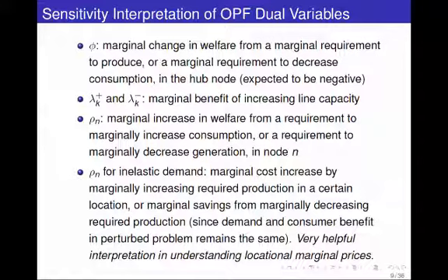How does the welfare change? This is the total net injection over all buses, so basically the total production minus the total demand. Slightly increasing the right-hand side says that the amount of power you're shipping to the hub minus the total consumption you're taking from the hub is not equal to 0 anymore. It's equal to something slightly bigger than 0.